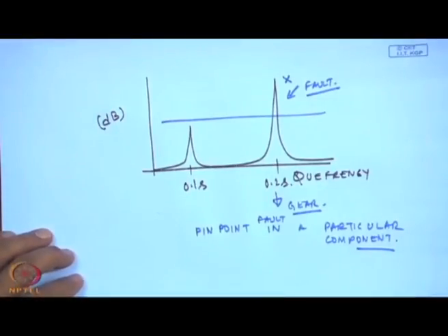Just to summarize, the gearbox is a very important mechanical component, and this device is used almost in every industry. Two broad ways of fault detection in gearbox are, one, oil analysis and wear debris analysis, another being vibration analysis.